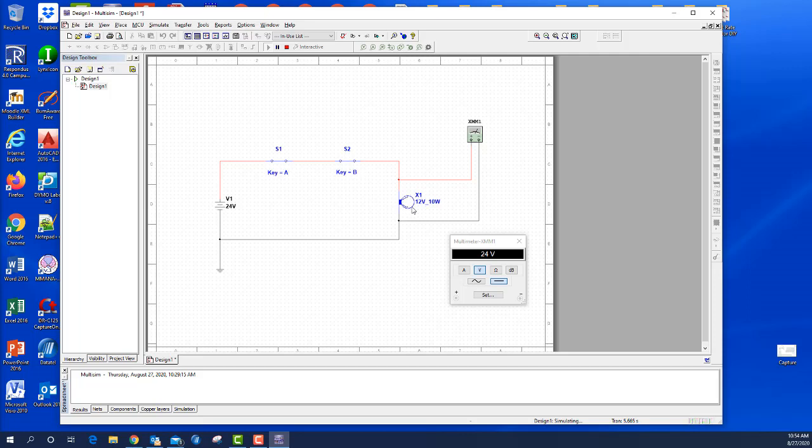My light's not on. Why is the lamp not on? We've got 24 volts there. Notice what happened to the lamp. You notice the filament burn out in the lamp? We just burned that bulb out. Why? Because it's a 12-volt lamp. You can't put 24 volts on a 12-volt lamp. It's going to burn it out pretty quick. In this case, it was almost instant.